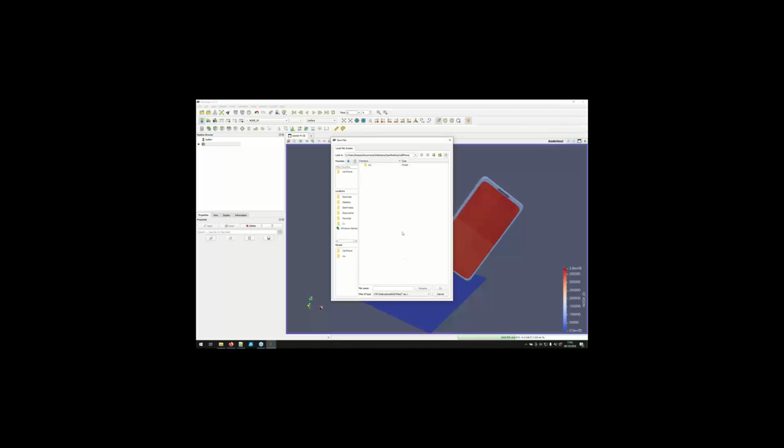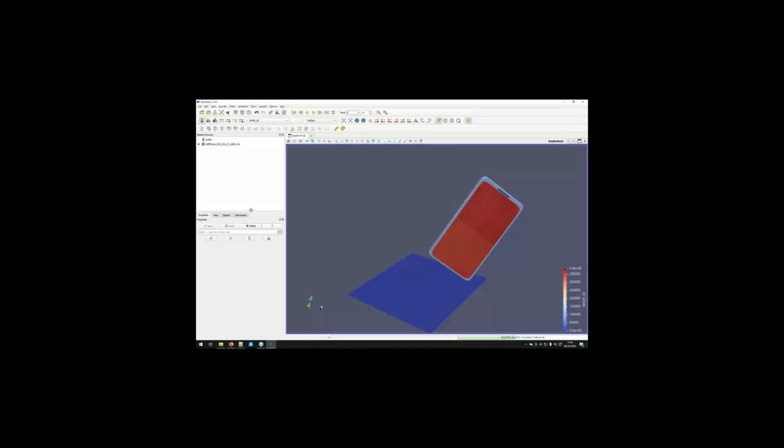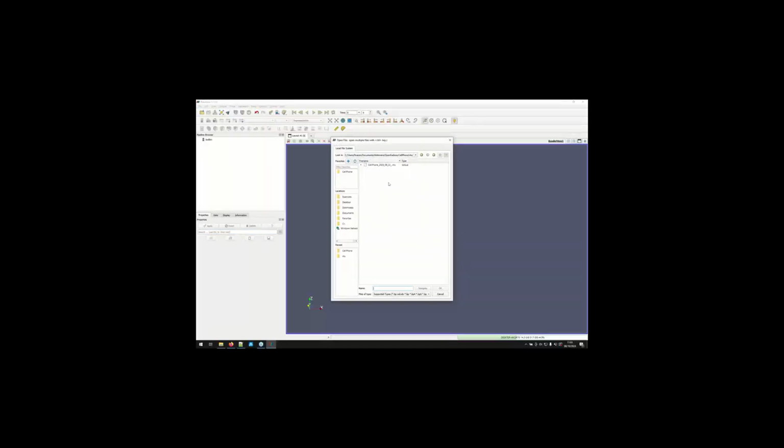much faster in ParaView. And the other file format that Kitware is working on at the moment is the VTK HDF file. HDF is a container dedicated to HPC, distributed file formats and so on. So stay tuned, we are working on it, and soon you will be able to export your anim file to VTK HDF in order to get more performance. So once you have converted your data to VTU, I will open what I have.